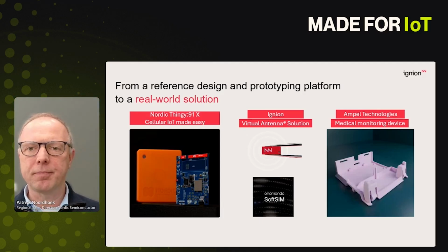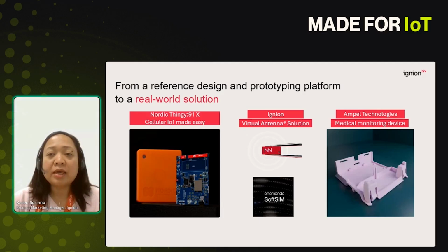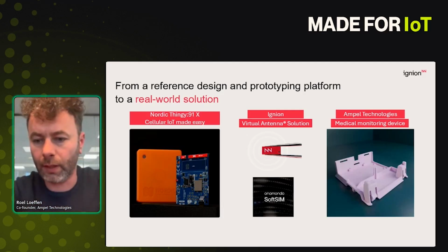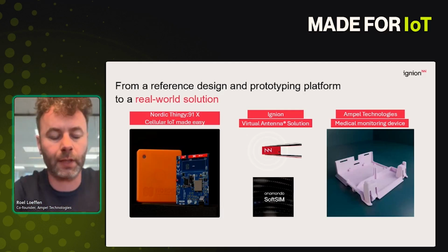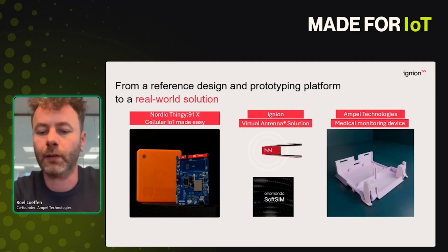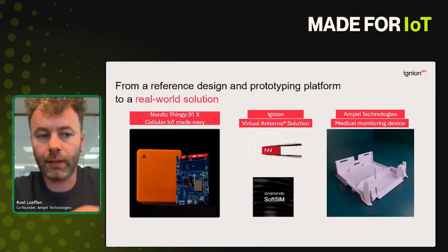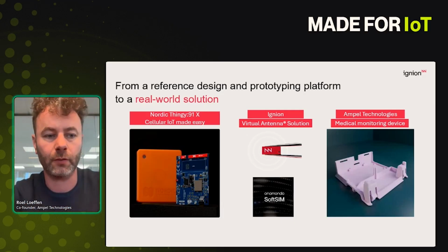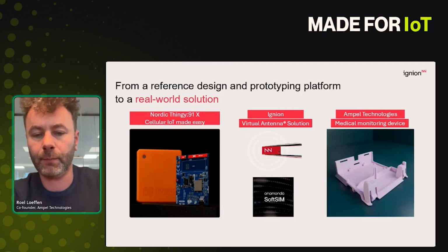All right. From David as well, he's interested to understand your payload and intervals as well as number of sensors. Yeah, okay, I can answer that. So for this device, we have to wake up once a day, and we stay awake for 1 minute. Indeed, like Patrick said, we use the deep sleep modes which Nordic provides us.